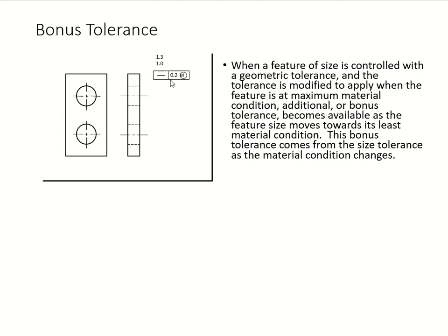And we put the additional material tolerance in addition to the regular one, yeah. So the one that I showed you in a previous example, when we put the datum here, I said, don't worry about it. That's because you have two different tolerances right there, meaning you have a bonus tolerance in it. So like the previous example that I showed you, don't worry about that. And why do we need the bonus tolerance? Again, in order for us to cover your material condition when it changes.